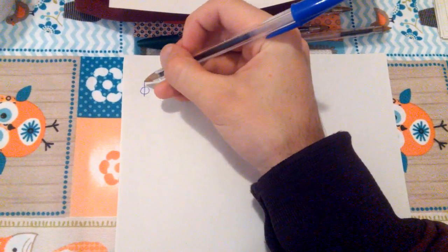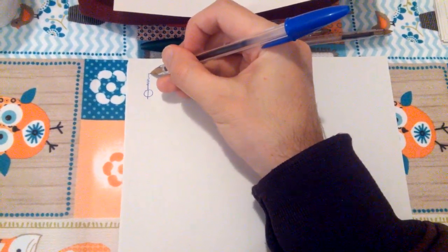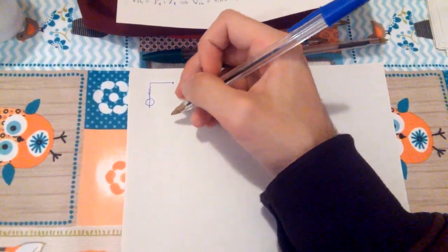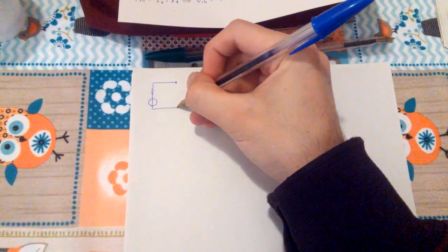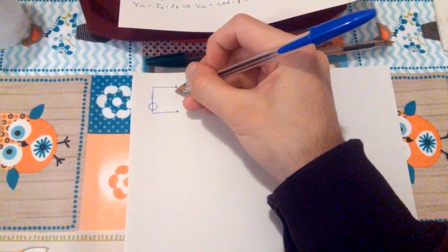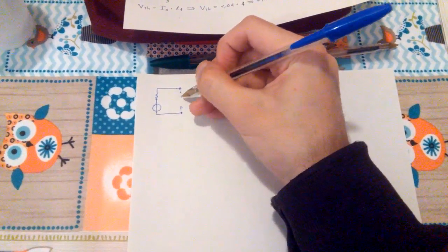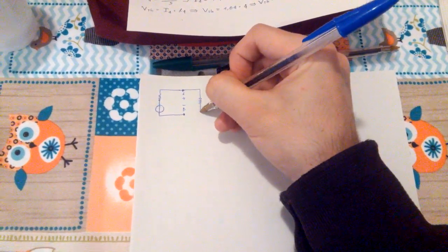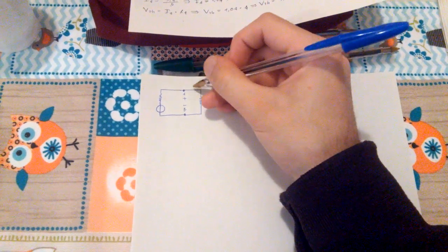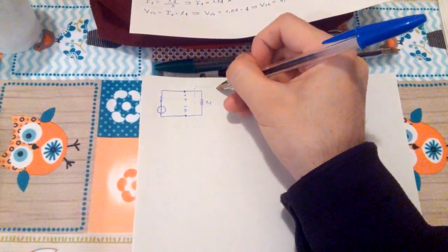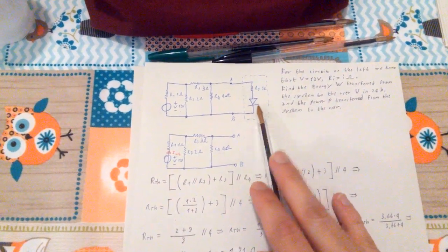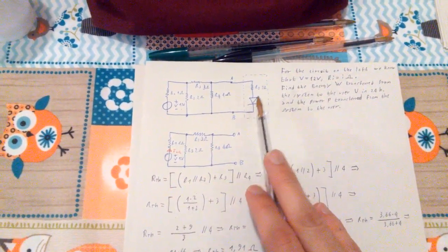So we have a voltage source in series with a resistor, just like by definition of the Thevenin equivalent circuit. Those two are going to be my points A and B. And down here, I'm going to have my resistor R5, like so. And I'm not going to have the diode anymore, because as I said, it's going to let the current through. It doesn't have any internal resistance, so I can just ignore it and go on.